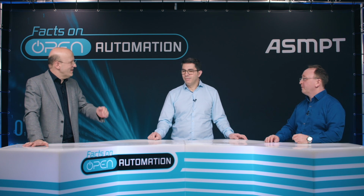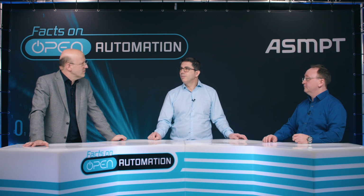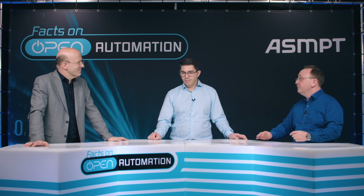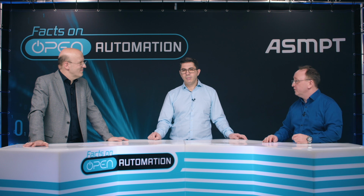Wolfgang, it's kind of ironic that you are here because you are the head of special applications. Your job is to design special purpose machines, yet we recommend general purpose machines instead of special purpose machines for such challenges. Why? Well, Laszlo, there are different ways to handle those components or processes. One is, of course, to use a dedicated, customized robot cell. This robot cell also has its disadvantages. It is highly dedicated and ideal for a specific process or component. However, to modify it so that it can handle other components or other processes is usually difficult or even impossible.